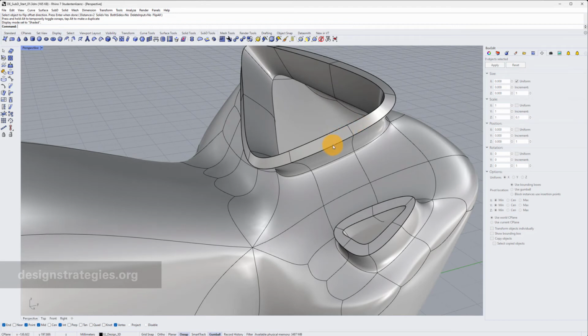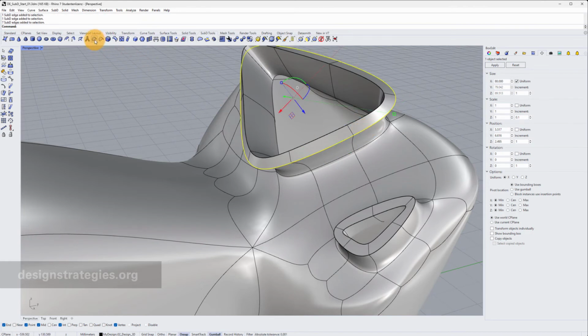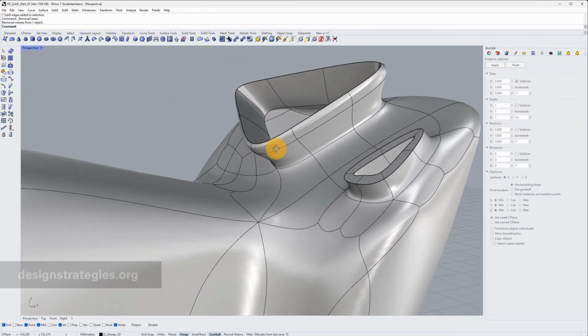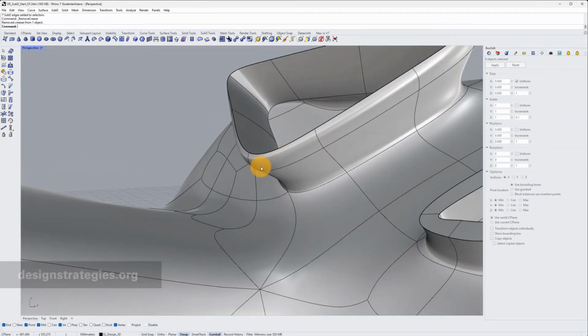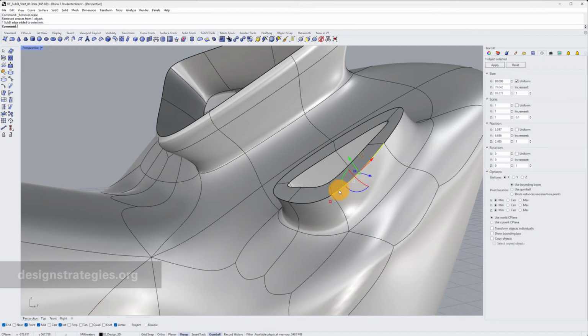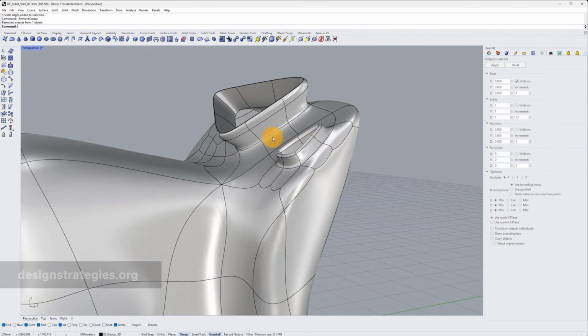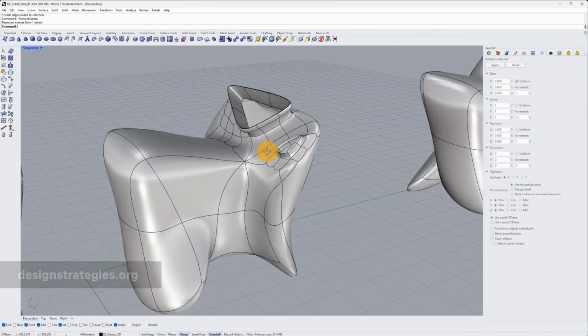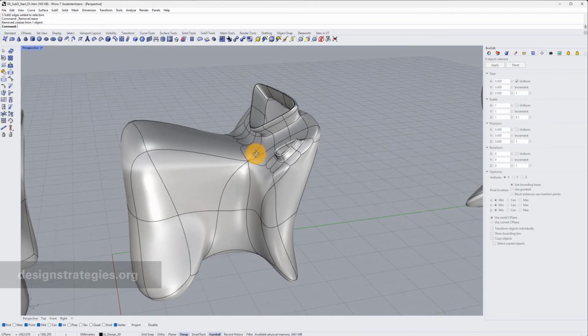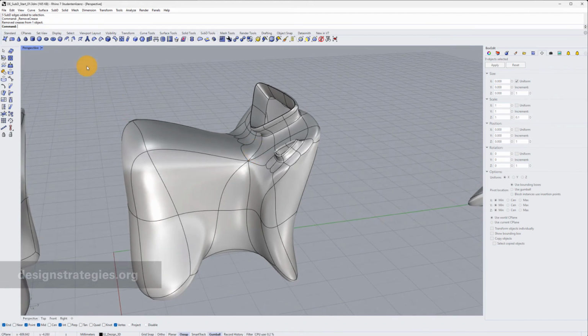But we learned how to do this. We just select one edge, I double click and select the other edge, and then you can just say remove crease. And now it already looks like this. It has one sharp corner, and to compare this, I just do it here on this side slightly different. I just select both and double click here, and I just go into remove crease, and then it already looks really nice and fragile regarding my 3D printing.